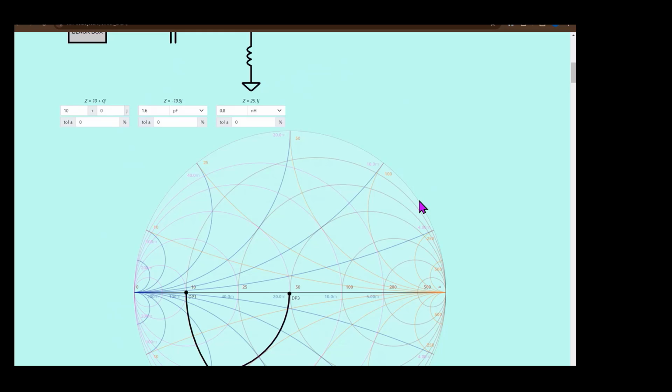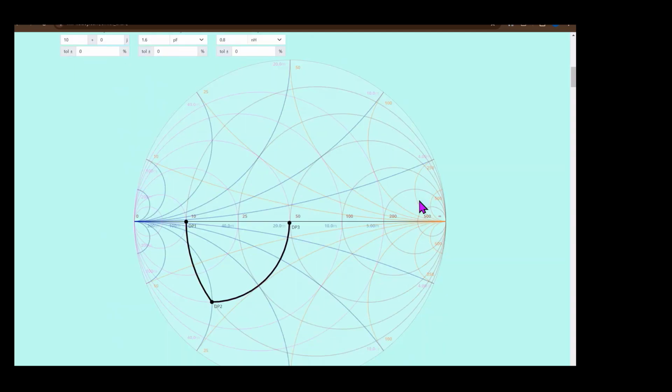Question? Yeah. Is there a way to quickly estimate the Q of this network in the Smith chart? So in this particular case, assuming the quality factor is equal to 0 for any purely real impedance, I'll assume that I got close enough to a real impedance here. The quality factor is just the ratio of the reactance to the resistance.